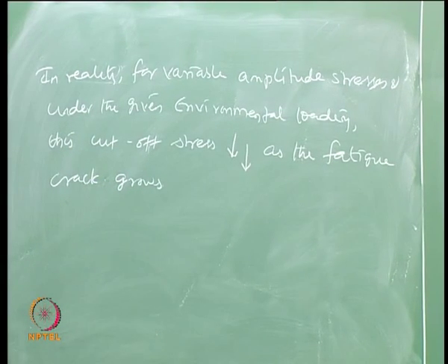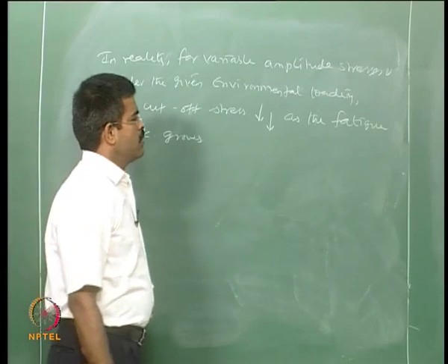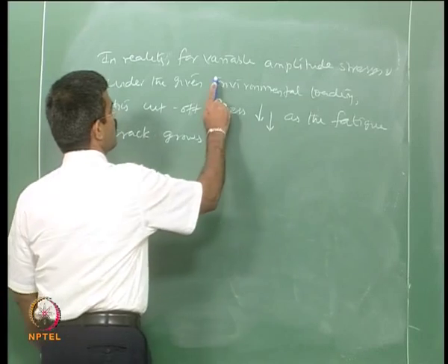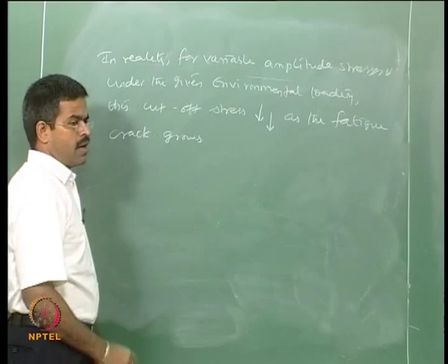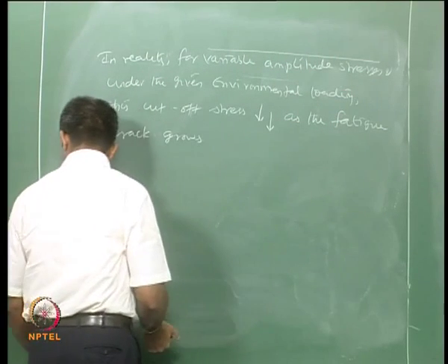So, there will be a reduction in this stress carrying capacity or the stress range capacity when they are subjected to real environmental loading and variable amplitude stresses.